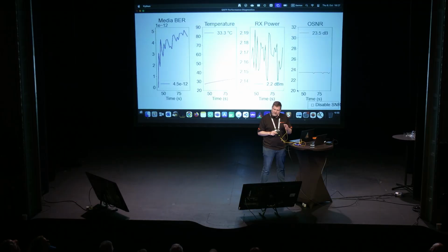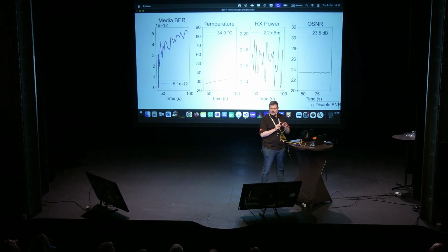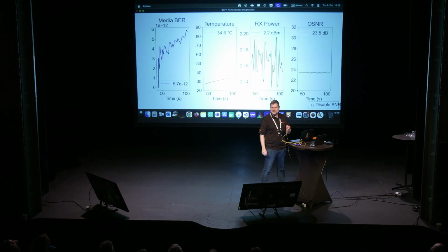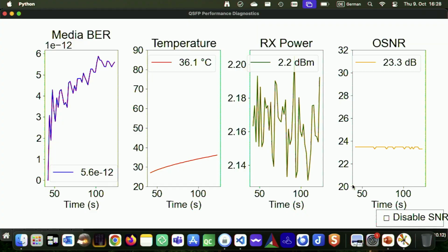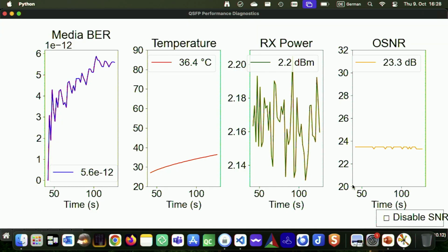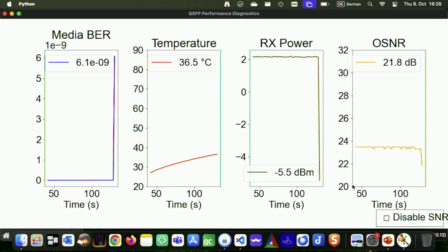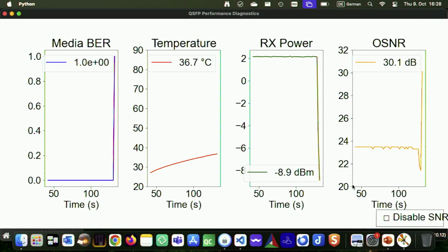Now, to see what happens if the signal gets lost, maybe a question to the audience. What is the lowest dB signal you can expect at X power? Has anybody an idea? If I bend this cable, what value would you get? What would be the theoretical minimum if there's no signal in dB? Minus 40, yeah? It's not the theoretical minimum. Theoretical is infinity, of course, but 40 is the conventional value to consider, because after that, you only have noise and you don't need to consider anything.